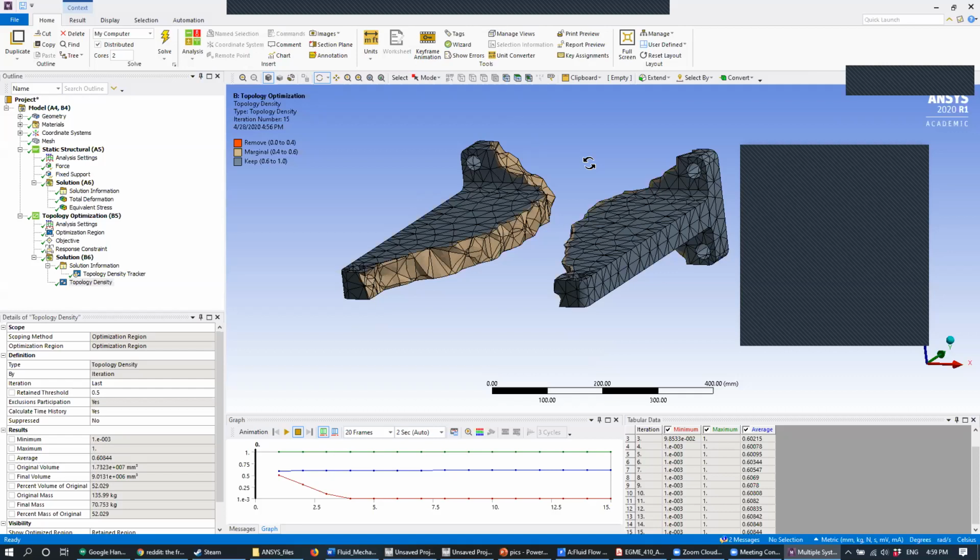I remember someone said last time that if you have multiple instances, it takes each instance and adds the total amount to the node count. So if you have a structural and a thermal, the maximum amount of elements for each is going to be halved, because the total adds up to 32,000.